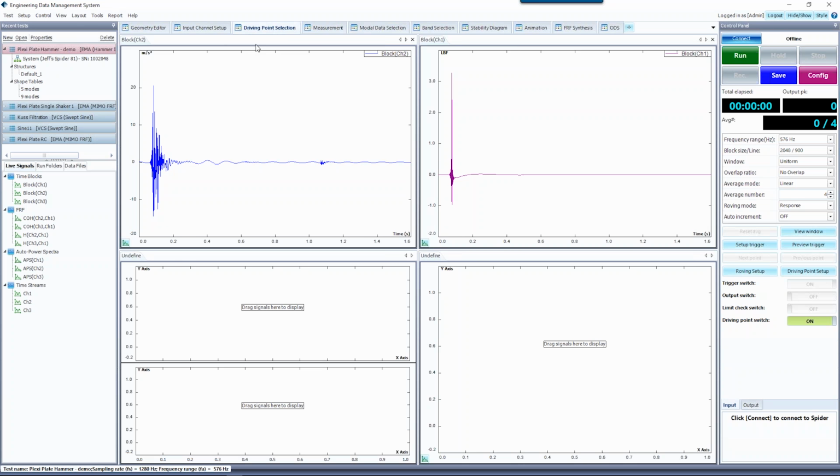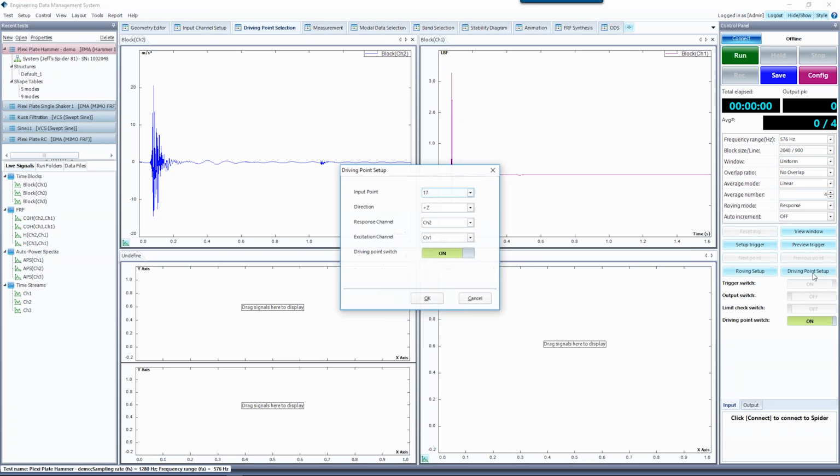If you're using a modal shaker, where do you put your drive location? The idea is that you survey multiple possible good locations. Because for modal testing, people all know we have node points, and depending on your structure, you have node lines. So you don't want to use these locations for your fixed driving point, or fixed reference point of response if you are roving the hammer.